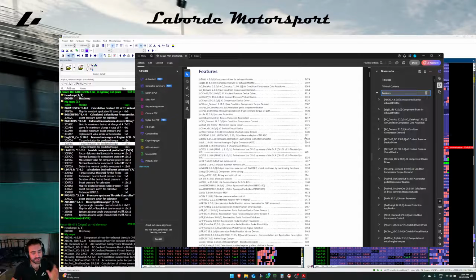and it should be pretty easy to find that way. So instead of looking directly for the engine speed variable, we're looking for a variable relating to a torque limitation map that is used between the two software versions. We should be able to look in the same data area, and there should be a read of the engine speed variable that the CAN bus one is derived from. And then we can go ahead, define that, manipulate it, test it, and see if that will work for what we need. Again, this might not even work.